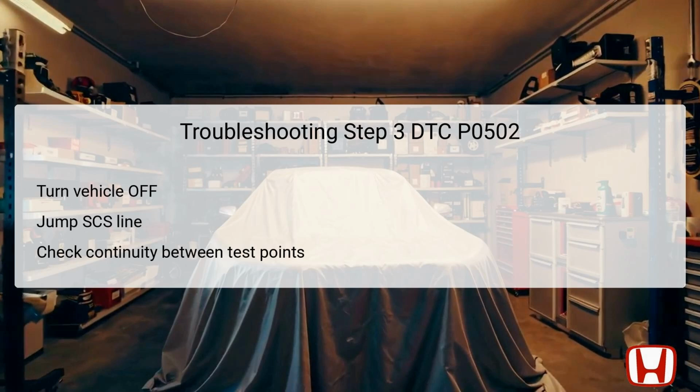Step 3 consists of a more specific open wire check focusing on the VCC2 line. First, turn the vehicle to off, lock, mode. To prevent any potential damage to the powertrain control module, PCM, jump the SRS, supplemental restraint system line, using the HDS and wait for more than a minute. Following this precaution, disconnect the PCM connector C, 51P.